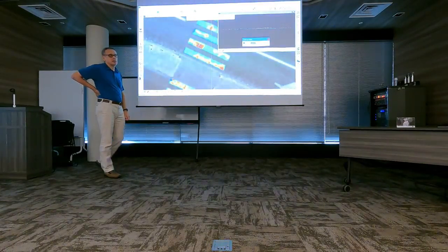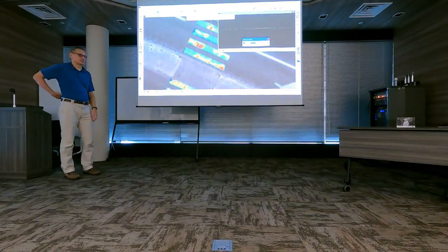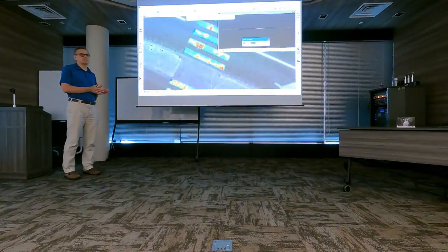So my polygon is not perfectly placed. I may have some point which is on the paint. I may have some point outside the polygon. It would make sense to have a little bigger setting than 1 centimeter there. Maybe 3-4 would be a good setting.